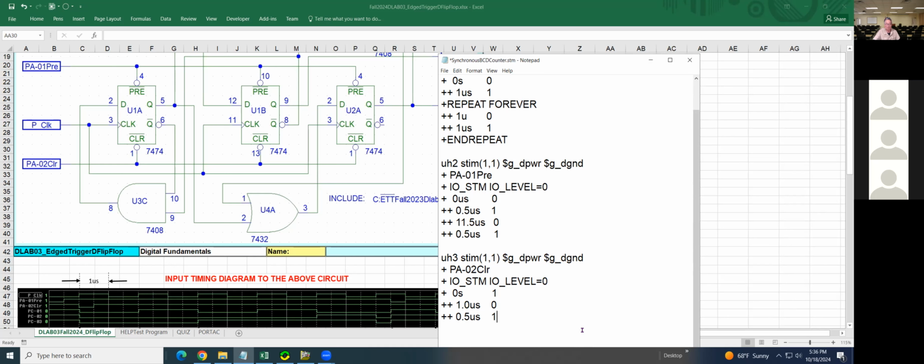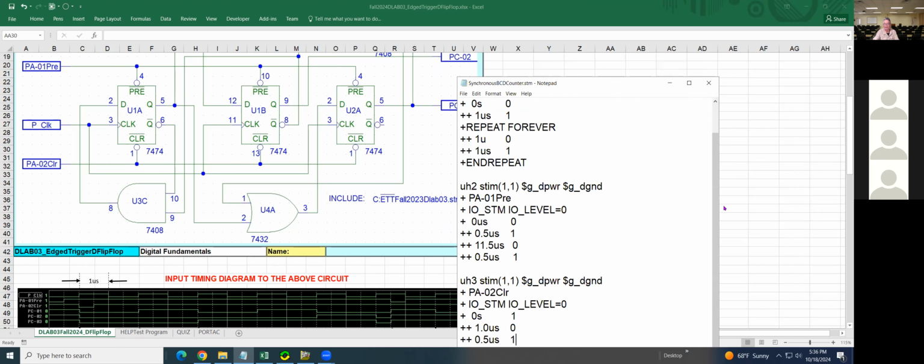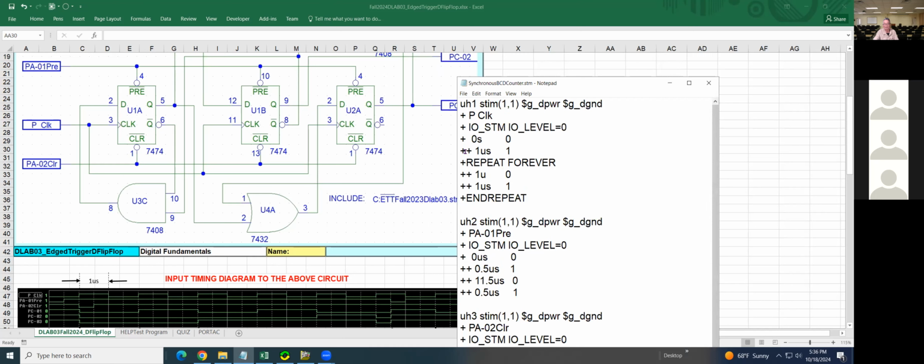Okay. Now the key point is after you are done with the file in here, never say "save as." This is a project. They are inside the project. If you say "as," that means they will be somewhere else. So they're not working. Remember that. You must click just "save" only. So that will be done. You see that? You can use it in any file. They already have it.